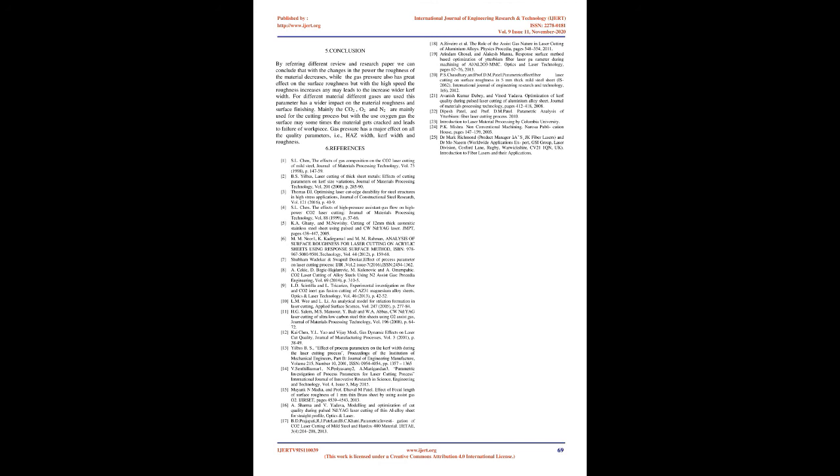5. Conclusion. By referring to different review and research papers we can conclude that with changes in the power, the roughness of the material decreases, while the gas pressure also has a great effect on the surface roughness, but with high speed the roughness increases and may lead to a wider kerf width. For different materials different gases are used. This parameter has a wider impact on the material roughness and surface finishing.